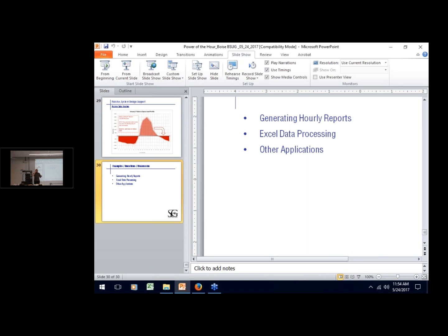Now you can specify a design day in eQuest where you can set whatever date you want. So if you wanted to say, I want ASHRAE design outside air temperatures, and I want to overlay that with sun angle conditions from the middle of August, now you're probably getting into the ballpark of the appropriate cooling design day, and you have a lot of pre-formatted reports that you can access that are usable. But I don't know of a way to get hourly reports.